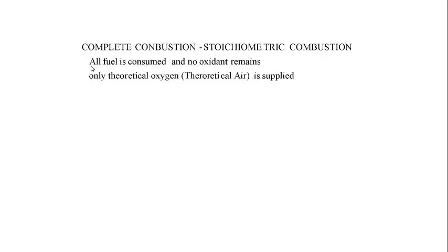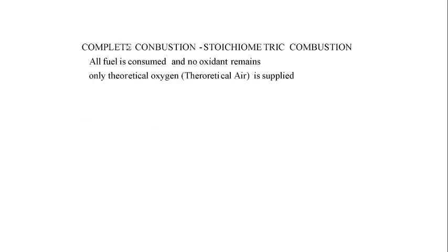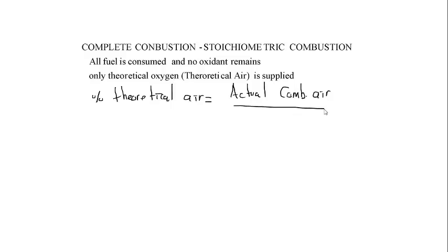So it's basically the amount of air that you need for complete combustion. There's a term called percent theoretical air. Percent theoretical air is the actual amount of combustion air that you have divided by the theoretical amount needed.